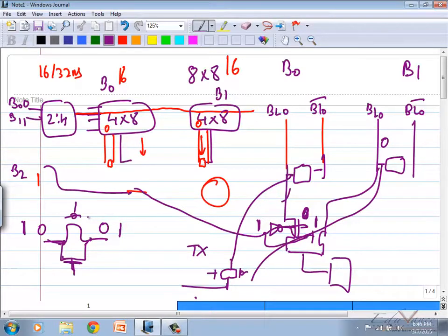But why am I discussing all these issues? So that in the future, if you ever give an interview based on memory design, you should be able to say, sir, here the precharge sizing is an issue, the pull-down circuitry sizing is an issue, the decoder sizing is an issue, the row decoder, the column decoder, what will happen if I split. This person will definitely ask this in the interview. What if I split this across two, what will happen? You should start talking then.